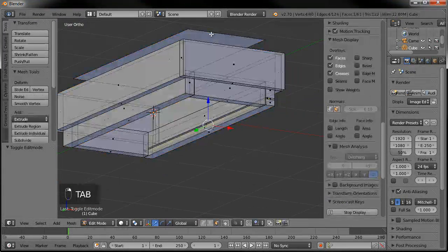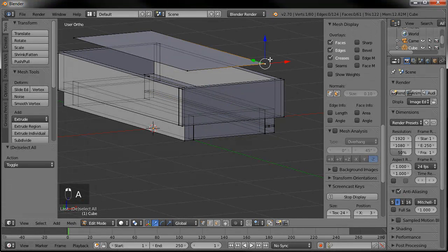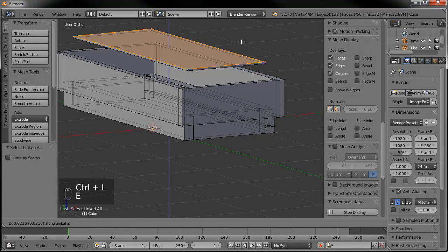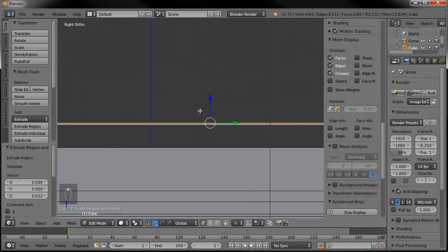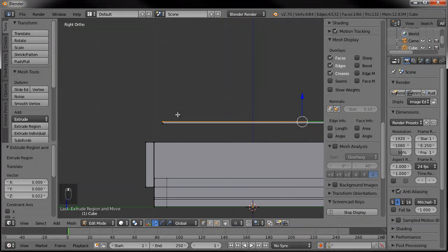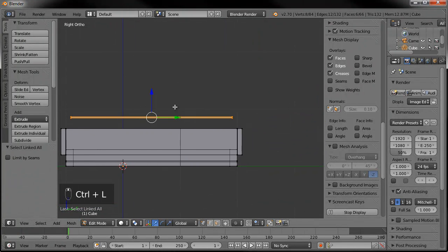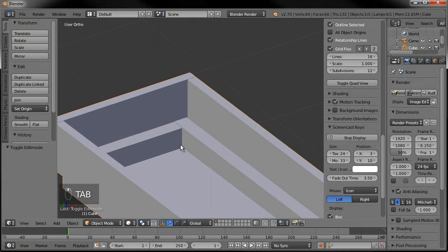And then our bottom, if I can, oh, I was trying to grab the corner, but the vertices weren't turned on. Let's extrude that up just so it's physical world. Now, depending on how thick you have the plywood, mine's about 1/4 inch, I believe, or let's see, 1/4 to 1/2 inch. I'd have to actually go measure it to know for sure, but we'll just call it in between here just for visualization. This part's not that important because it's just the thickness, and as long as it fits in that groove we just created, it should be fine. So this will be the ground board. We go ahead and put that down into that like so, and it'll fit there all around.